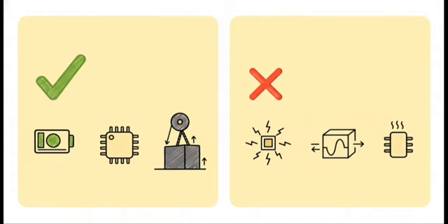But there are downsides. It does create high-frequency noise, or EMI, that can mess with other electronics. The raw output is choppy, so you pretty much always need a filter. And while it's efficient, switching things on and off millions of times a second does create some energy loss of its own, which can be a problem at super high frequencies.